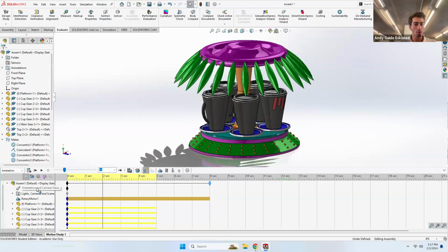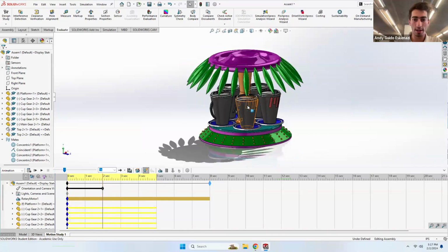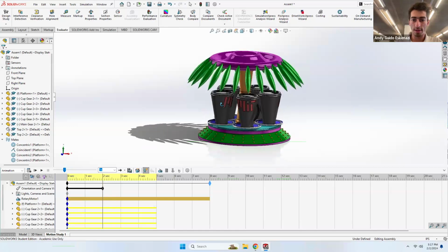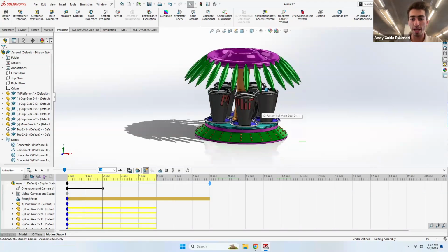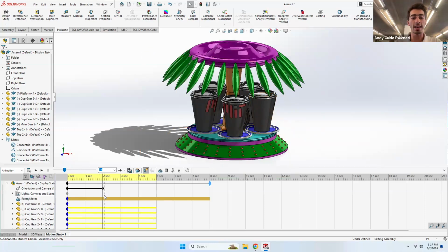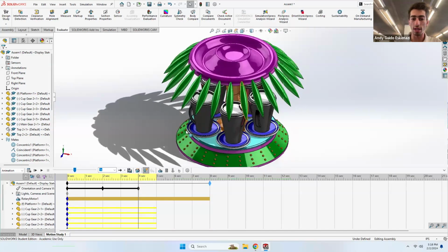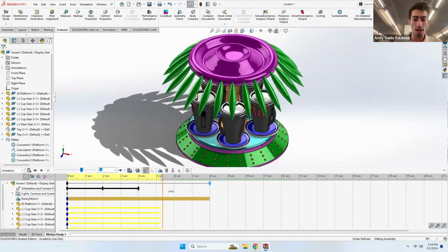If you go to orientation, I can right click in there and it says disable view key creation. I'm gonna actually click in there. And now, for instance, say I'm here, right? So I can change, I can correct my orientation, right? And you see that now it's creating a key. Then I can go to second floor and say, all right, I actually want the view to change to be like this. And it's actually dynamically changing.